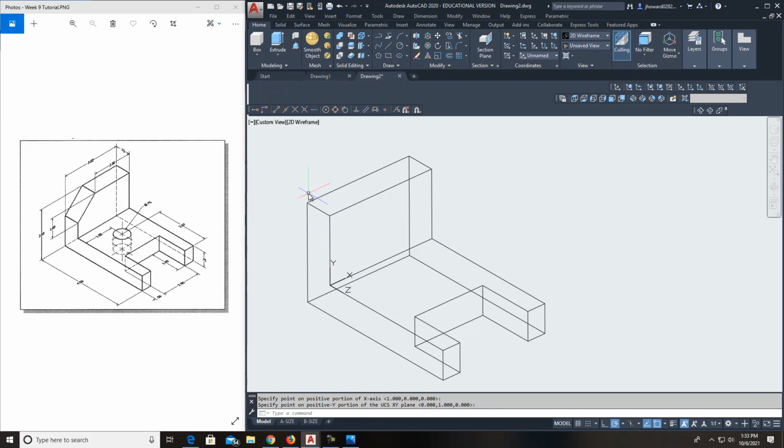So what I want to do is just hit line or offset. I can do an offset, 2 inches over. So offset of 2 inches. I want this one to come over. And it's probably not wanting to do that, is it? Well, I could always just click right there and come over 2. Enter, just like that. I made myself a line, and then here it's 1 inch from the top. I can go here and come down 1, just get it going in that line.